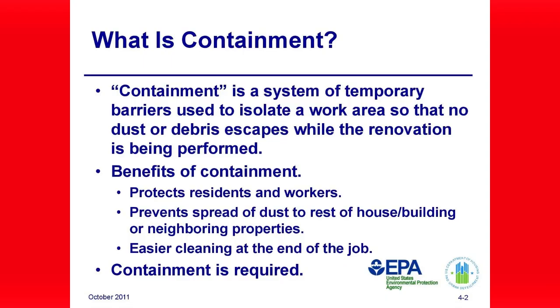Closing windows and doors and using plastic sheathing to seal doors and air ducts in the work area. Covering doors used to enter the work area with plastic sheathing in a manner that allows workers to pass through, but containing the dust and debris within the work area.